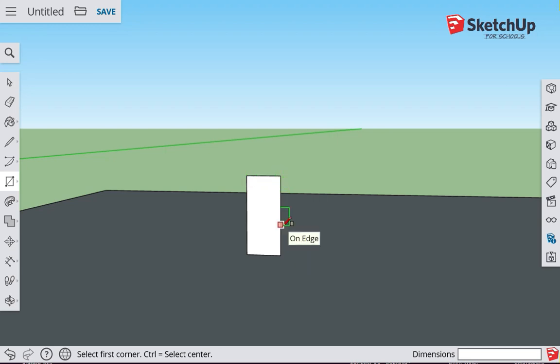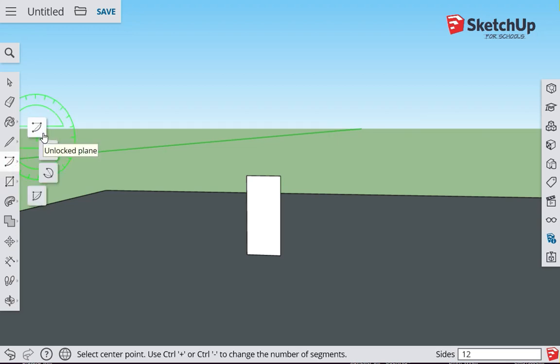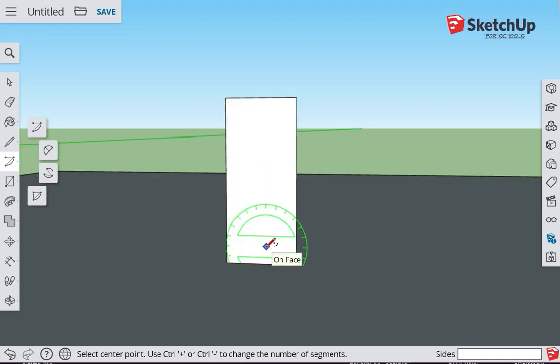And in that, we're going to create the curve of our cup. We'll do that next. So we'll use the arc tool, and the one I choose to use is the standard arc tool as opposed to the 2-point. Okay, so with the arc tool, well, this is where it gets tricky. I'm going to zoom in quite a bit.